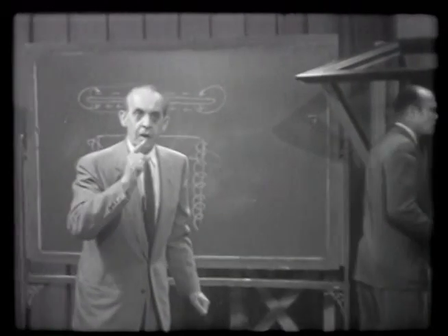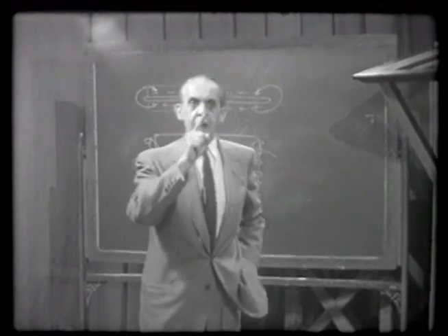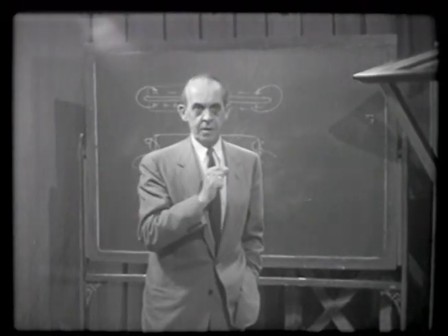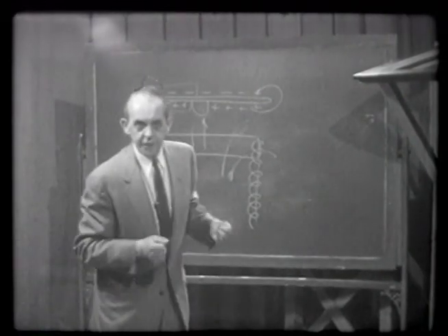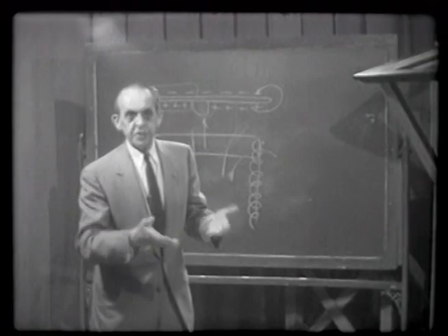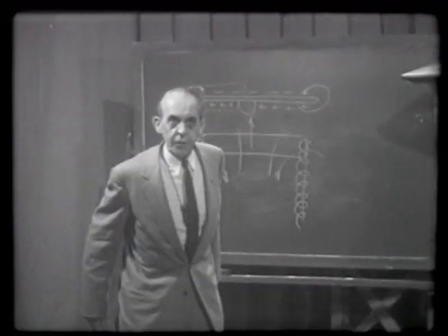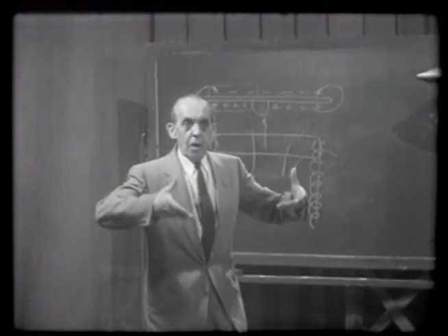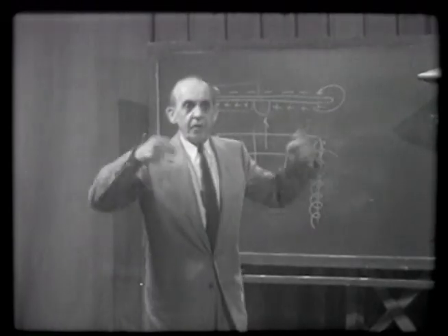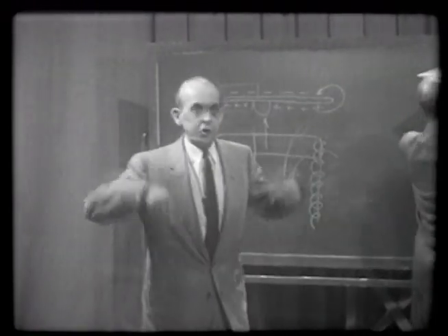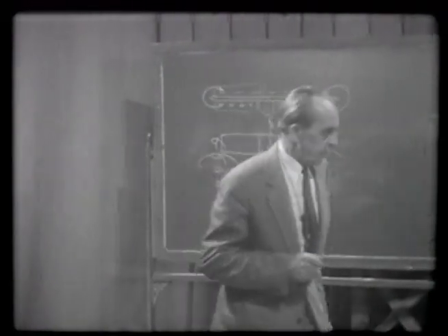You will then observe one thing. Well, as long as we have no lift, we wouldn't have any pressure differential, because then pressure on both sides of the wing is the same. So the result is that we wouldn't have any of these curls on the side, these wingtip vortices. If we have more lift, we get vortices. The moment we increase lift, the vortices must get stronger and stronger. And this we might see here pretty well.